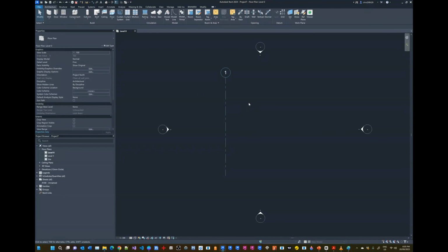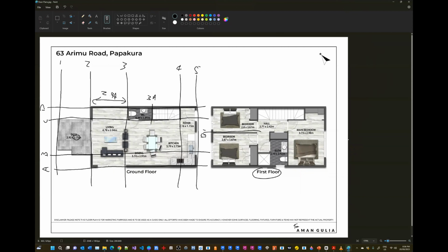The next one we'll have to compute a little bit. So here we've got 2.91 meters, and then we've got 2.73 meters, and then there we've got 1.19 meters from that line. So let's say that we first create grid line 4 here. So I'm going to open up my calculator quickly, and I'm going to type here 2910 plus 2730.